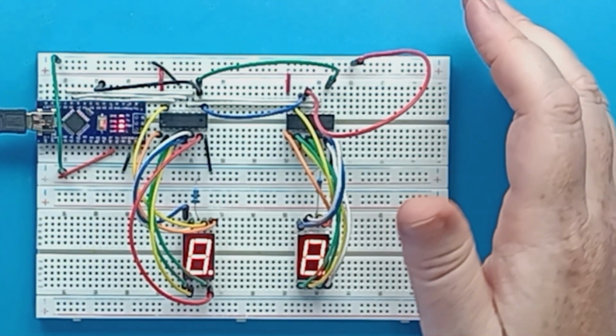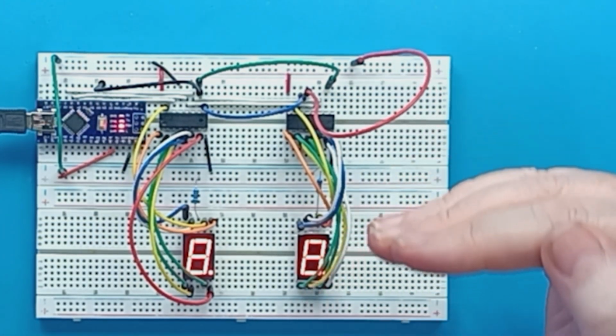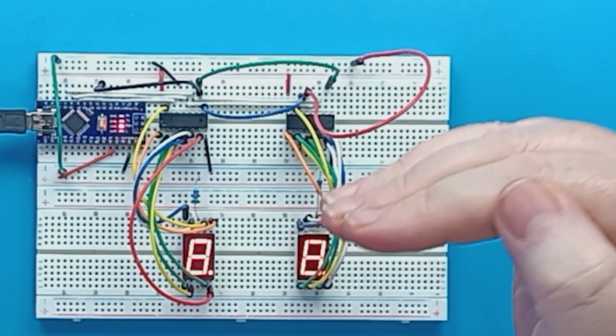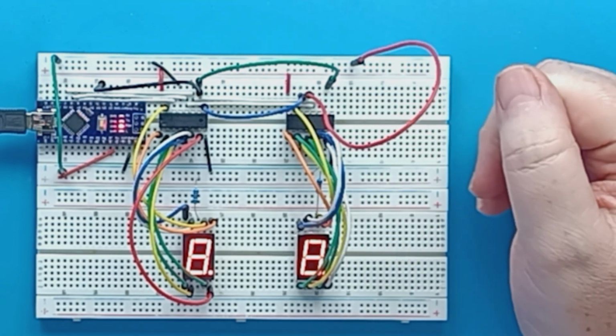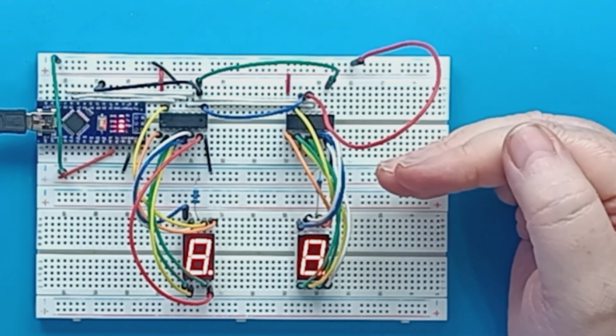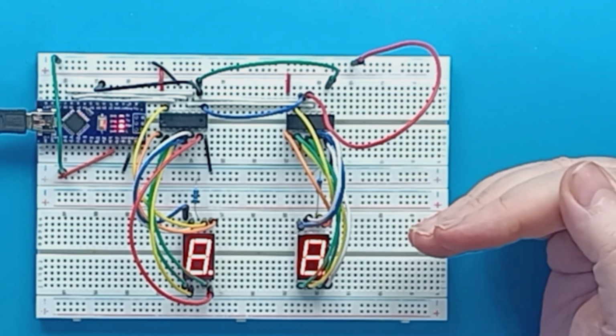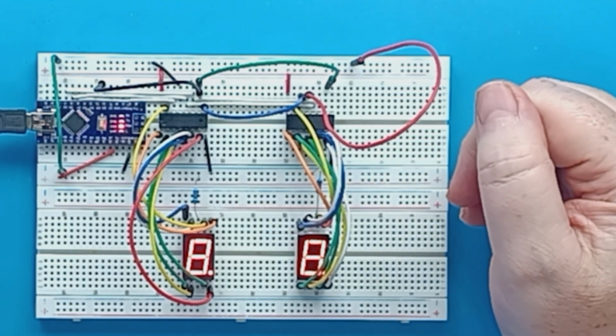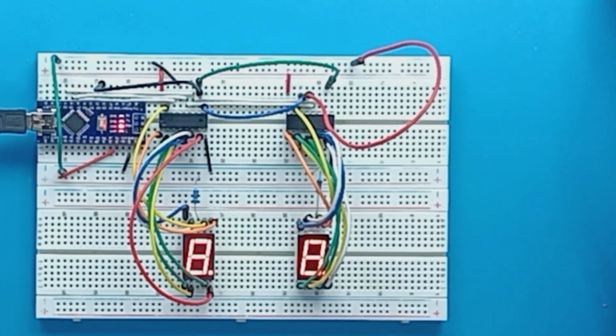If you're using, instead of an SIPO device, a parallel input serial output device, it's basically the reverse of this, where you have a parallel input set which gets read serially. That enables you to have many digital inputs going through into the 4 wires.